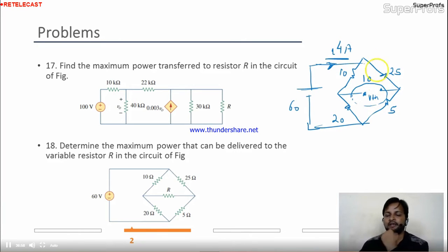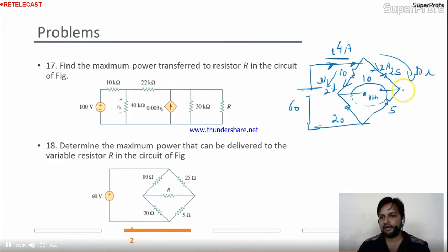This is 4 ampere. Now 4 ampere current is coming from the source. Here the current will divide. Here the current is getting 30 ohm, here the current is getting 30 ohm, means current will be divided into equal amounts. So here we are having 2 ampere. In this branch also we are having 2 ampere. This 2 ampere current is coming over here. So here I am having the drop of 10 volt in this direction, plus minus. Here 2 ampere is coming. Here is 40 volt.